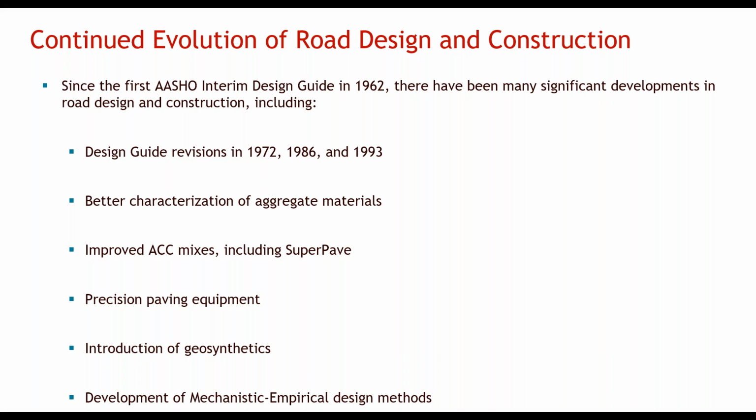We have much better paving equipment now than we had in 1958, and geosynthetics have been introduced to pavement design by Tensar and others, including geogrids, geotextiles, asphalt interlayers, and drainage composites. Two of the most recent developments have been the development of mechanistic empirical design methods and the development of in situ test methods. That is, the ability to test the strength of materials after they have been placed in the field, as opposed to relying on previous tests. We'll cover mechanistic empirical design briefly and then conclude our presentation for today.